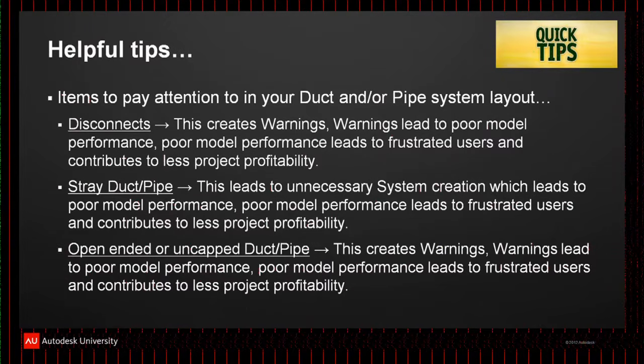One thing I'll throw out there about the conversion, especially if you're doing vector files, it's not nested. It's like the old days of AutoCAD where you have to purge through. Yeah, that's a good point. So the comment over here, I'll summarize, is don't think that a single purge will be enough to solve your problem. It may take 4 or 5 purges to get everything out.